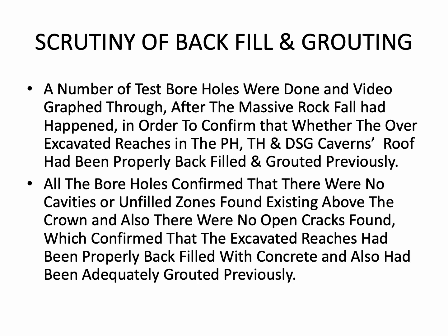At that stage, it was taken upon to do scrutiny of backfill and grouting. A number of test boreholes were done and videographed after the massive rockfall had happened, in order to confirm whether the over-excavated reaches in the powerhouse, transformer hall and downstream surge gallery caverns roof had been properly backfilled and grouted previously or not.